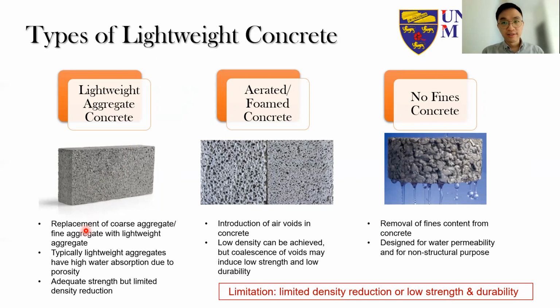But nevertheless, in this kind of lightweight aggregate concrete, we can still get a good amount of strength. But another issue is that the density reduction in this kind of lightweight concrete is usually also limited, where we cannot really reduce it to a very, very low density.